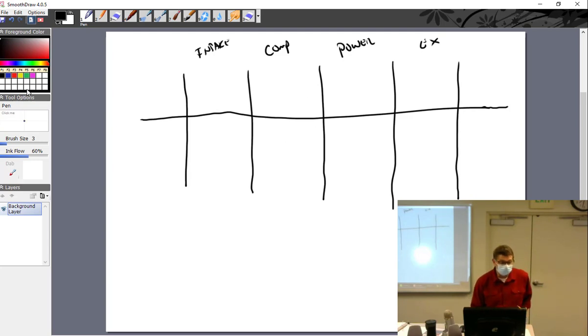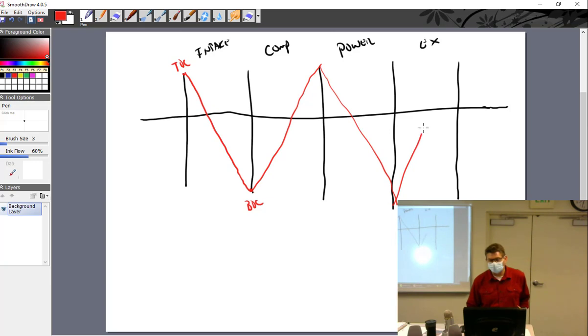And I can use this as my piston. Intake: piston goes from the top to the bottom. And that's my piston travel right there. So this down here is bottom dead center, and this would represent top dead center. Then from compression, it goes from the bottom to the top. You see what I'm doing here? All right, down and then up. So that's my piston travel.